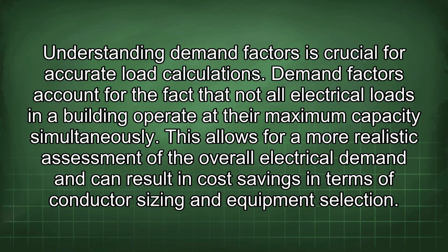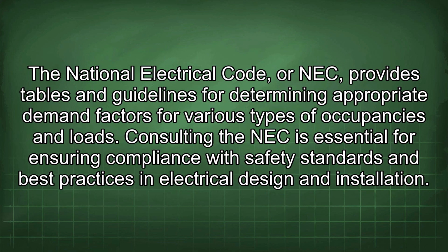Understanding demand factors is crucial for accurate load calculations. Demand factors account for the fact that not all electrical loads in a building operate at their maximum capacity simultaneously. This allows for a more realistic assessment of the overall electrical demand and can result in cost savings in terms of conductor sizing and equipment selection. The National Electrical Code, or NEC, provides tables and guidelines for determining appropriate demand factors for various types of occupancies and loads. Consulting the NEC is essential for ensuring compliance with safety standards and best practices in electrical design and installation.